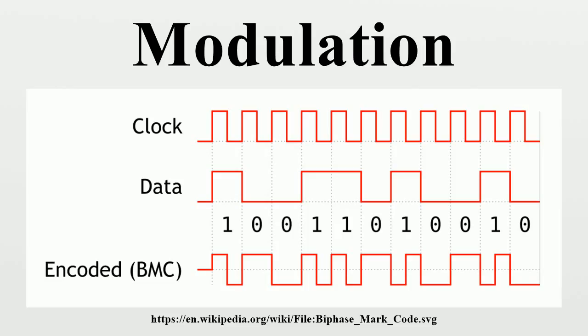If the symbol rate is R symbols/second, the data rate is R times n bits/second. For example, with an alphabet consisting of 16 alternative symbols, each symbol represents 4 bits. Thus, the data rate is 4 times the baud rate.